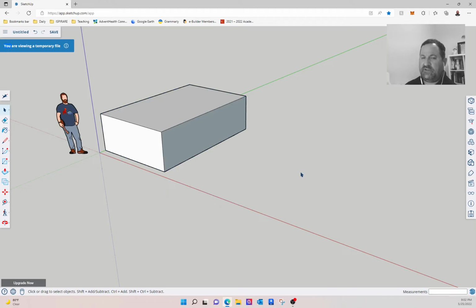I'm going to show you one more selection that I think is valuable. Using this selector tool, if I just left click once, it selects the surface because that's the thing it's touching. If I double click, it selects the surface and all the surrounding line work. In other words, this whole polygon, the closed polygon. If I triple click, it selects the polygon, the surface, and all connected surfaces and polygons. In other words, effectively, what I've been able to do is select everything all at once with just a triple click rather than a crossing window. So I use this element most often.